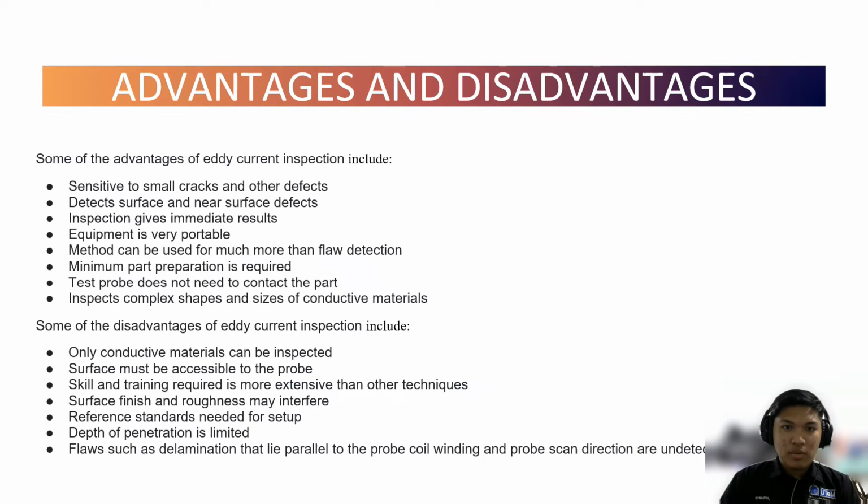Okay, some of the disadvantages of eddy current inspection include: only conductive materials can be inspected. Surface must be accessible to the probe. Skill and training required is more extensive than other techniques. Surface finish and roughness may interfere.